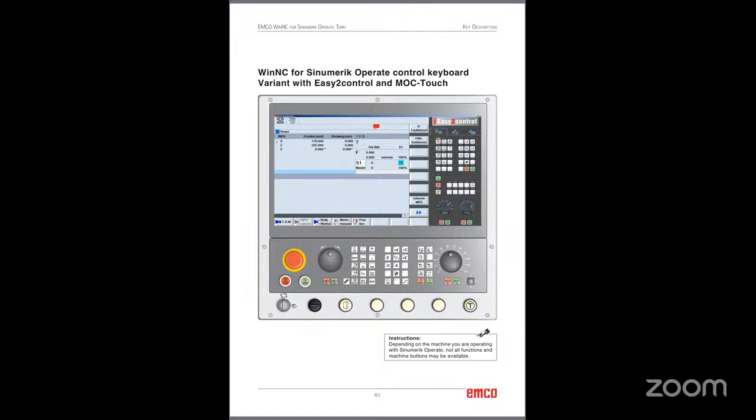Below that, we have a soft key area, so that we can select new, open, save, delete, etc. Then we have the message area, alarm messages, position display, machine coordinates. For example, what is the X value, what is the Z value. Even though we don't have a physical keyboard, the touchscreen will open the keyboard. We can write the program by just typing directly onto the screen.